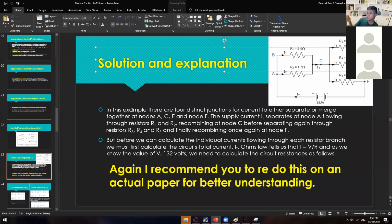So, solution and explanations. In this example, there are 4 distinct junctions for current to either separate or merge together at nodes A, C, E, and F. So the supply current I sub T separates at node A, flowing through resistors R1 and R2, and then recombining again at node C before separating again through R3, R4, and then R5. And then finally recombining once at node F, or at this node.